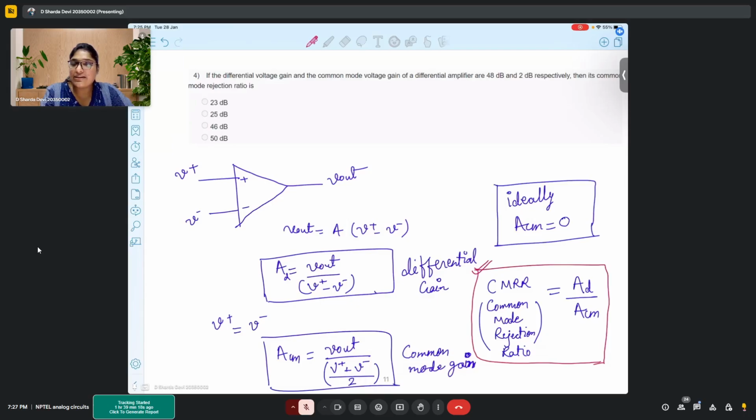That is a question, right? So the idea behind using a differential amplifier or differential input based amplifier was that any signal which is common to both the terminals could be nullified, right? So what could be these signals which are common in every case or common to both the terminals? What type of signal could it be?